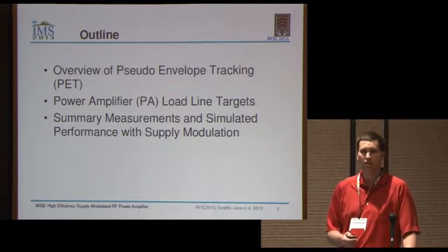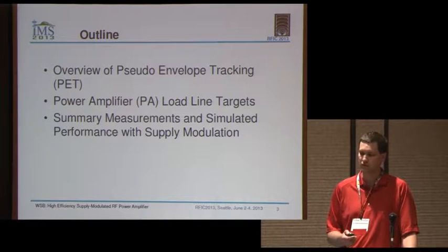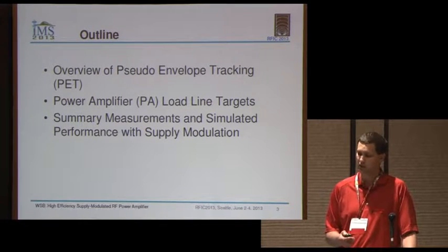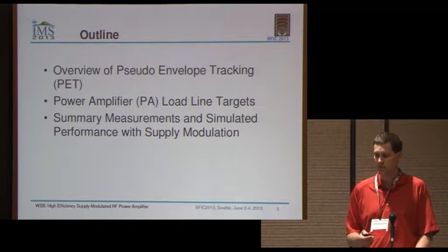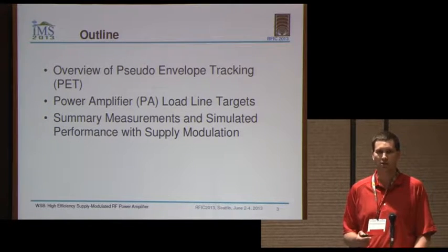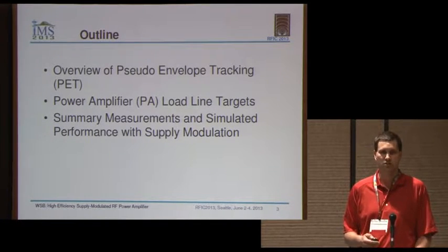So let me start off with an outline of the presentation. I'm going to give an overview of pseudo envelope tracking, and then I'm going to develop that into setting power amplifier load line targets for the envelope tracking PA. And then in the end, I'm going to provide some summary measurements of the envelope tracking PA along with some simulations of ET performance using the PA.